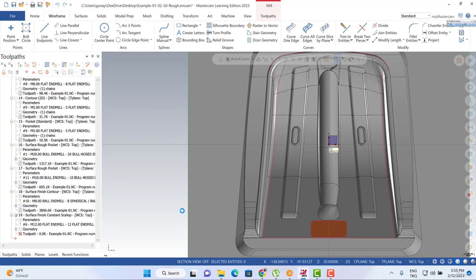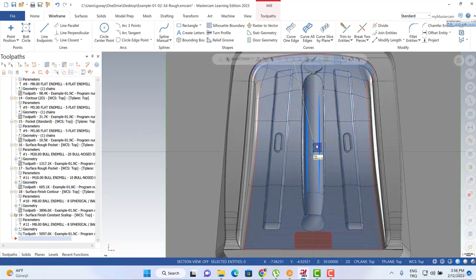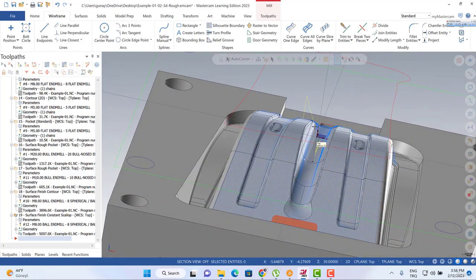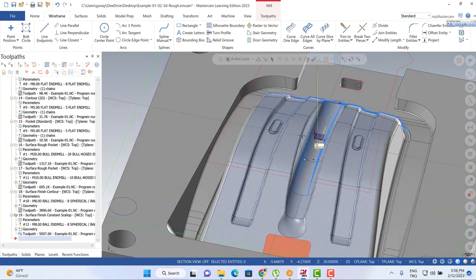After that, we can change my step over. So this is also quite important, and one of the tricks while you are calculating your toolpath. As a first step, you can write step over 1 millimeter, and then after that you can turn to your toolpath. If everything seems fine, you can change the step over to the real one. The calculation process can be time consuming most of the time, so maybe that's why you don't want to see that kind of stuff.